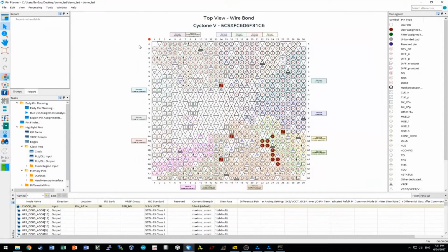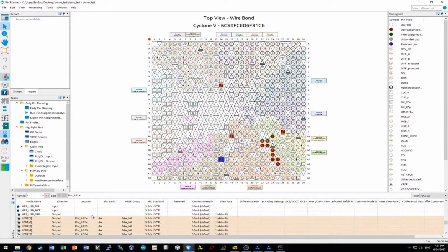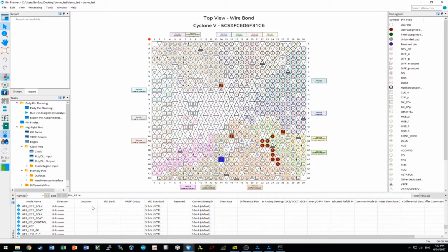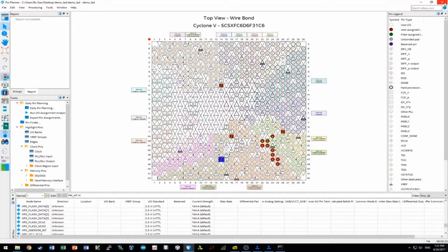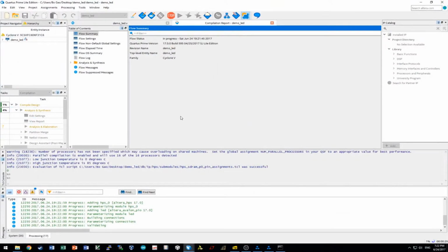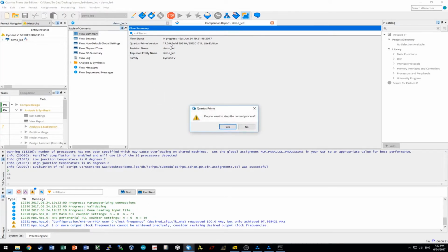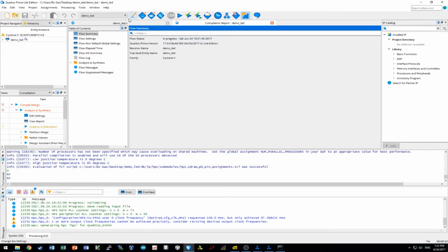And by the way, in your pin planner, this is already set by the System Builder. I mean the Terasic tool, and these are already set by the Terasic tool. And these are non-used pins, and they will just be dismissed. You can manually delete them, or you can just leave it there. I don't really care about that. Well, let's just delete that.